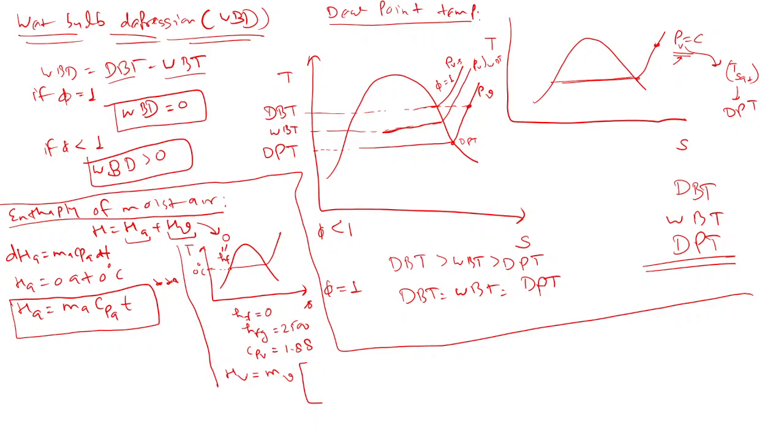we started from here, and now it will take latent heat, because our water vapor is usually here, in the superheated region. Is it clear? Yes, sir. So latent heat would be there, because HF we have taken here as 0. So latent heat it will take. After that, this sensible cooling at the vapor stage would be there: latent heat plus Cp of vapor into T. So T would be our dry bulb temperature. Here also dry bulb temperature.